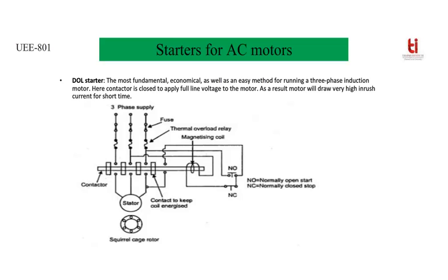It is the most fundamental, economical as well as easy method for running a three-phase induction motor. Contactors are used to connect the three-phase supply with the three-phase stator windings. You can see the fuse and thermal overload relay. These are used for short circuit as well as overload protection. So these are separate issues to solve. But the contactors here are used just to provide a path from the three-phase supply to the three-phase stator side.